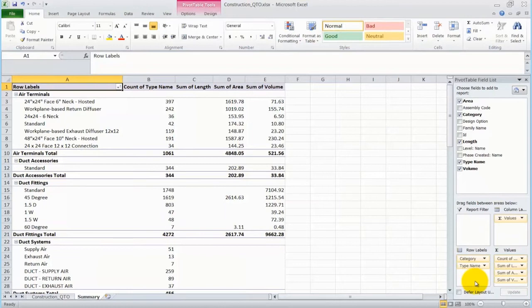This is a good example of how people are using Ideate BIMLink: they're extracting data from Revit, putting it into Excel, and many times they're just massaging the data, or formatting it in a way that makes sense. In this case, it's easy to see and easy to format these nice little pieces of summary information with an Excel pivot table. And then this could be used in a report, or you might want to use one of our other products called Ideate Sticky to take this table and place it back into the Revit project.